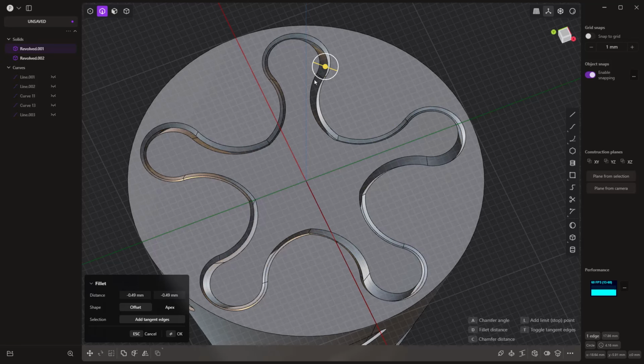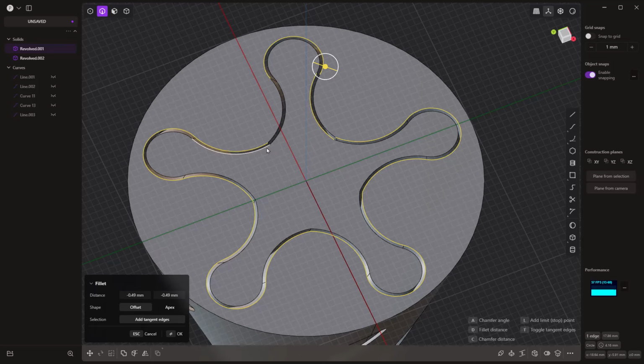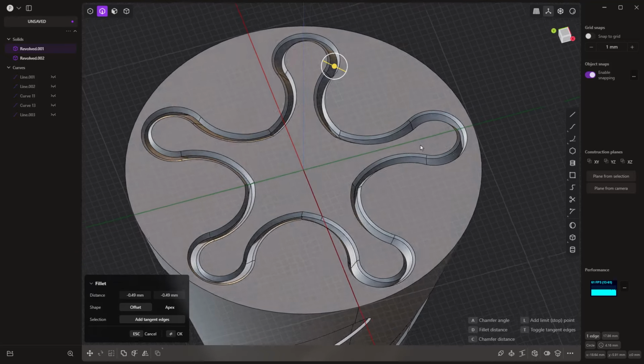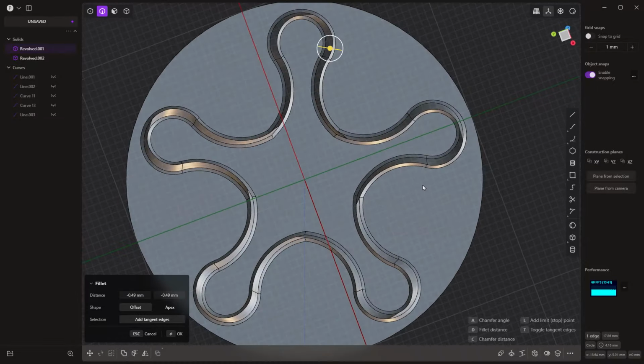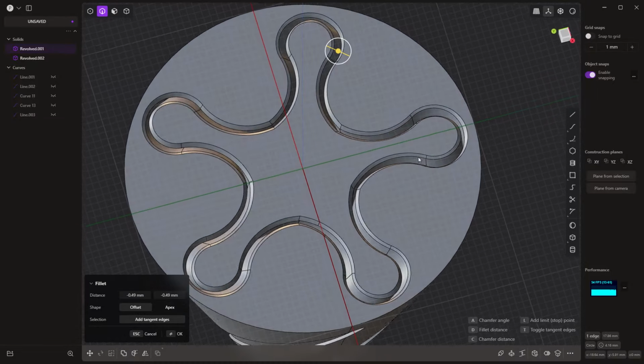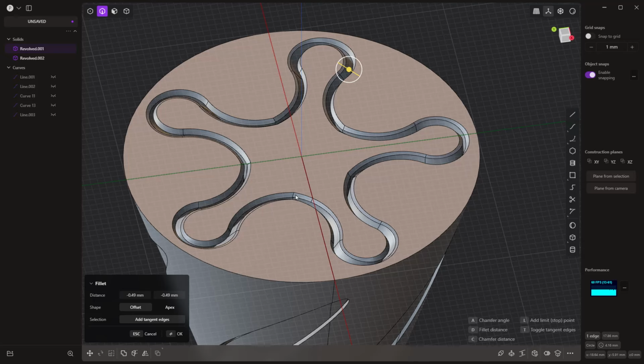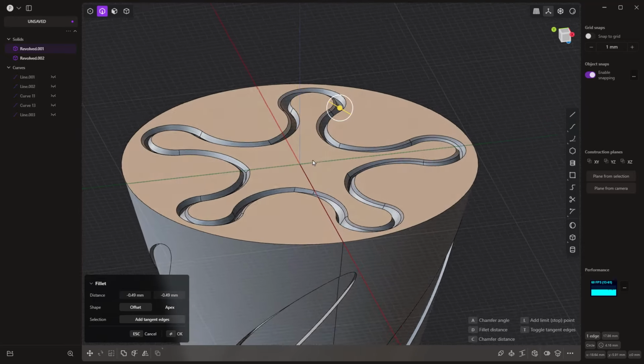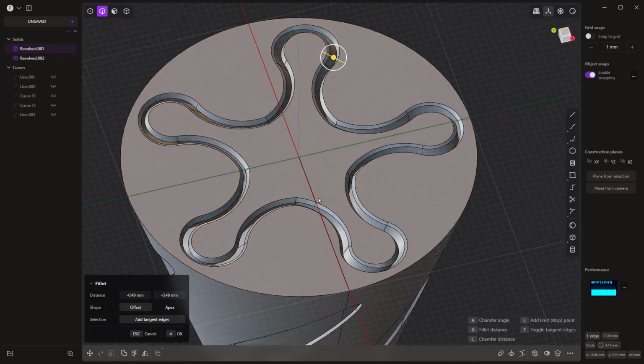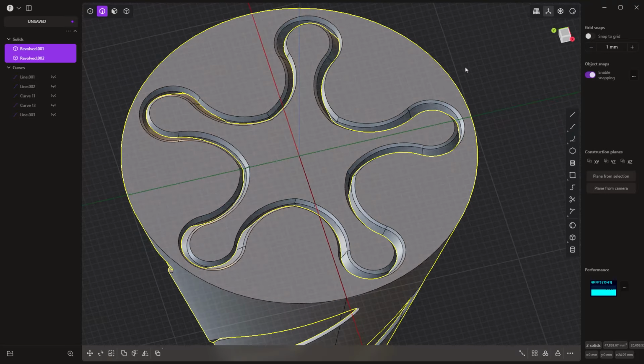We can also do this on the inside part. Again, you will need to go across all of the different seams because there are those hard transitions. Let's see if we got them all. Yeah, and this should still 3D print just fine. It's 45 degrees. If you make it too small, then you might not have the resolution to make that happen, but this will make sure that they slide in and out of each other quite a bit easier. So right click to accept.